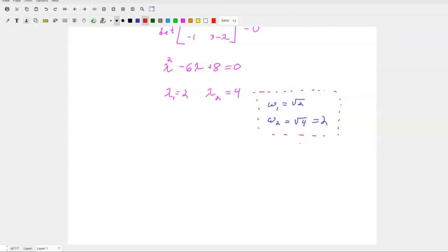All right, solved our eigenvalues. What's the next thing we want? Vectors. And what do vectors give us? Mode shapes, right? So, solve for eigenvectors. Well, that's easy-ish. K tilde minus lambda 1 times I is equal to 0. This is going to give me my first mode shape.